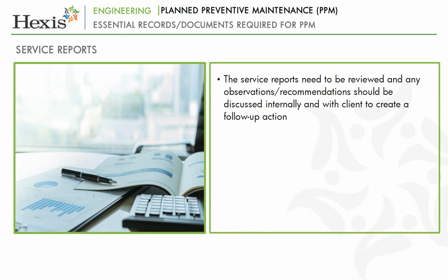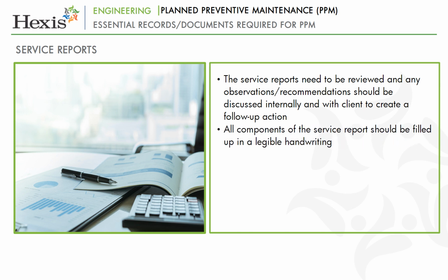The service reports need to be reviewed, and any observations or recommendations should be discussed internally and with the client to create a follow-up action. It should be ensured that all components of the service report are filled up in legible handwriting, and if any testing is done post-maintenance, the parameters should also be recorded.